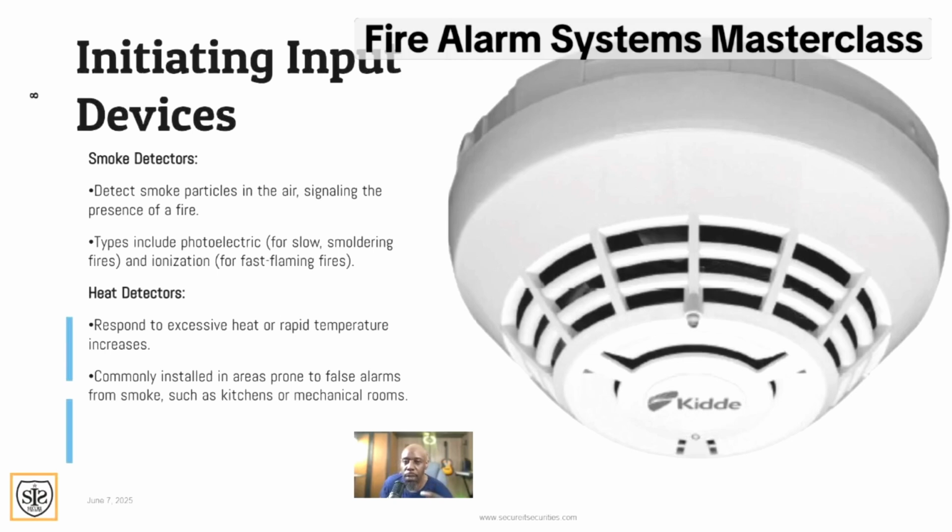And what it's doing is it's actually speaking to the CPU, just communicating back and forth, letting them know I'm still here. There are no troubles, or if there are any troubles. So this will flash green approximately every 90 seconds. So each smoke detector, each module, everything that's connected on a data loop will in fact poll every 90 seconds.